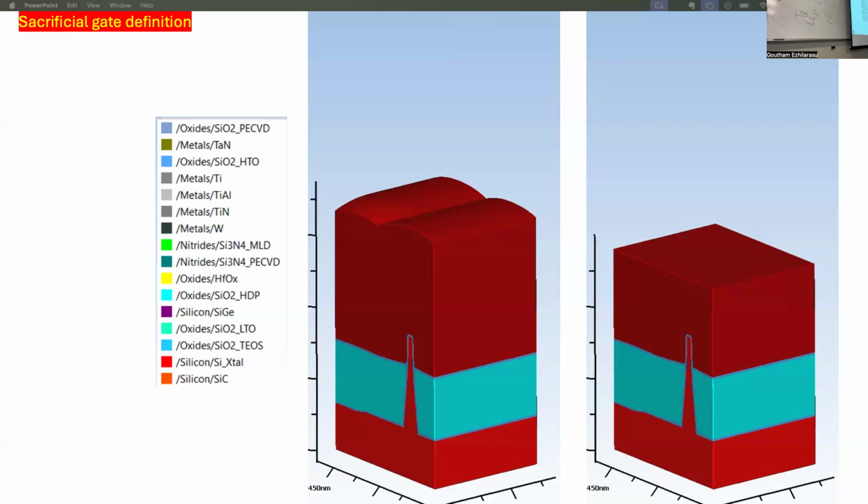But what you'll do is, say this was polysilicon first, right? You fill some kind of oxide and then you CMP down. So the oxide is over here like this. Then you etch away your polysilicon. And then you do an ALD hafnia and then metal, and then you CMP down. And then it's filled only here, and everywhere else goes away. But you don't need a mask to do that because it's just defined in the place where your polysilicon was originally present, right? So that's the replacement gate process. Yeah.